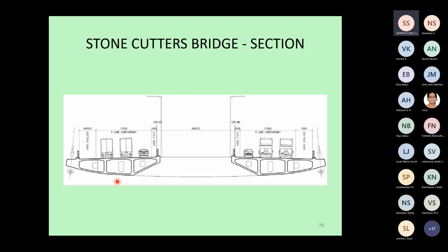And for wl square by 8 or whatever your bending moment theory, for 1 kilometer you get huge bending moments. And that has to be taken by such a horizontal load, the depth of the structure is measured horizontally, from this end to this end, like that. And you can see the vertical load supporting cables here and here, both ends, running to the tower. Probably they are anchored directly onto the deck.